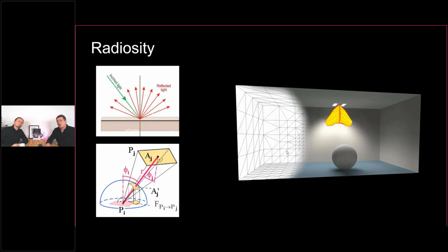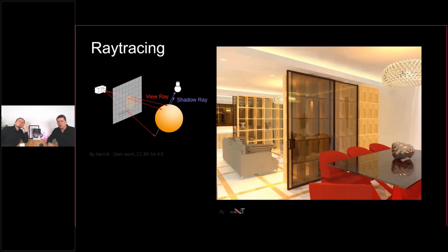One point then: because of this diffuse reflection, we can rotate and walk through the calculated room. This is one of the advantages of this radiosity method. The next point we want to present is ray tracing. This is a second alternative calculation kernel which we have had in RELUX since the beginning. And with this ray tracing calculation, it is also possible to calculate mirroring and transmission materials.